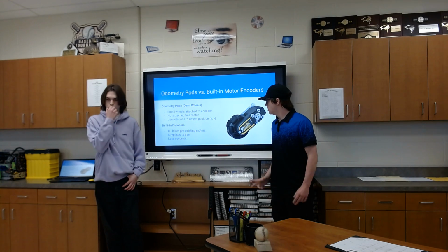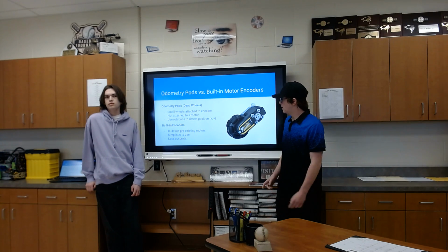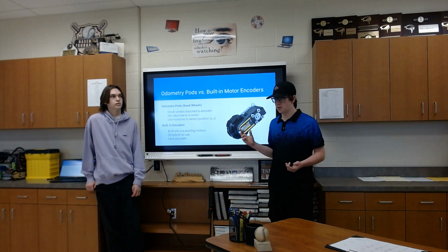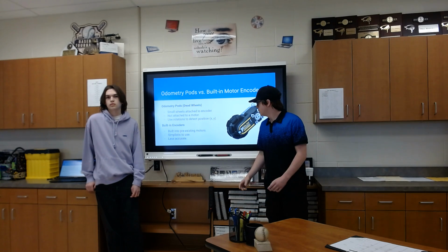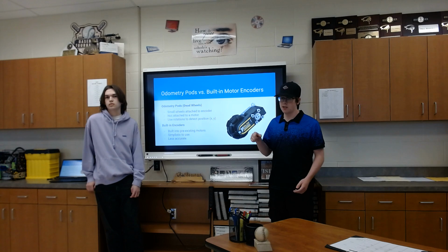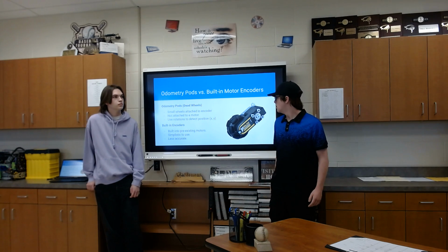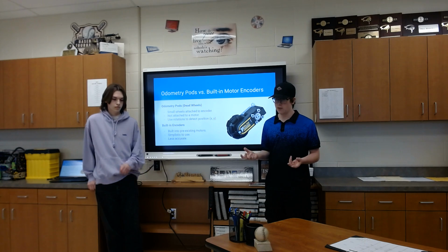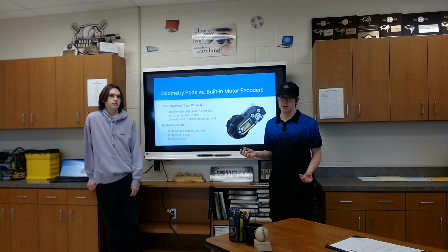So, odometry pods versus the built-in encoders with your motors. The odometry pods are a standalone thing. They're not attached to your motors, so there's no difficulty with that. They're very accurate and use the dead wheel rotations to track your X and Y coordinates on the field as well as your yaw. The built-in encoders use the pre-existing motors, so you don't have to buy a new component. They're very simplistic to use, but they are less accurate and they're prone to wheel slip.